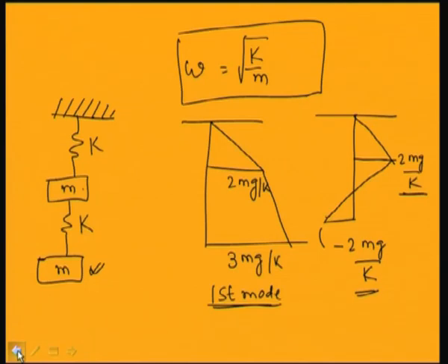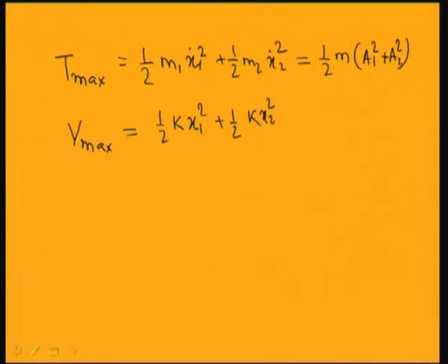Let us see, this spring has a displacement of x1, where this is x1 and this is x2. This spring will have a displacement of x1, but the second spring will have a relative displacement of x1 and x2, so this will be x2 minus x1. In case of the second spring the energy is half k times x2 minus x1 square.